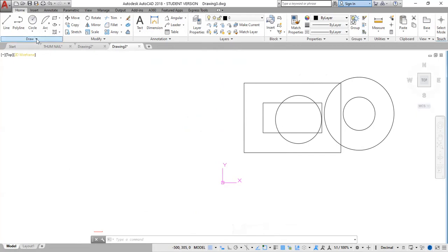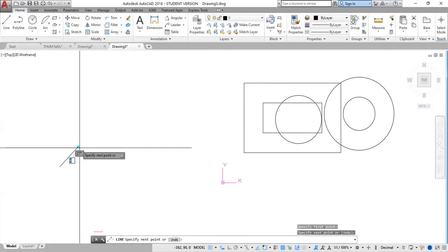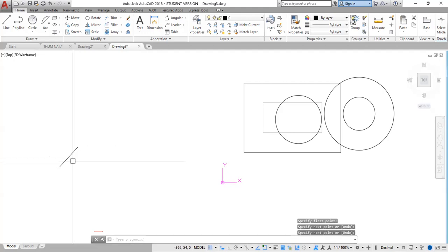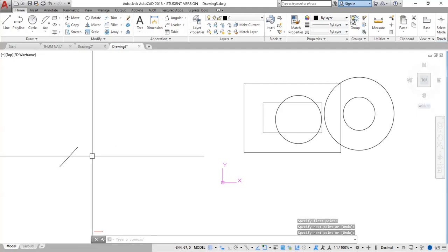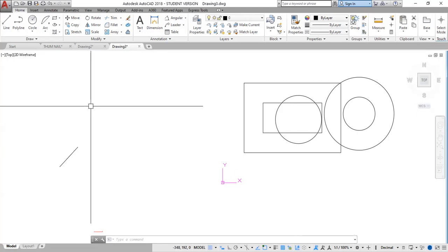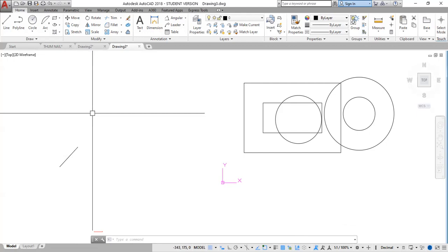Now it's important to note also that we could lengthen a line by a specific amount, by a specific value. Say, for example, I draw a line this length, this much, and I wish to lengthen this line to, say, 100 millimeters. I would use a special command called lengthen. So I would type Len for lengthen, and it pops up here. I click enter to accept lengthen.